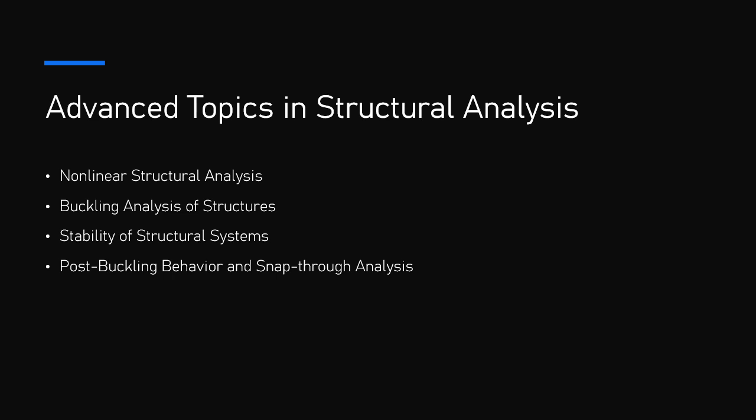10.2. Factors affecting buckling. Several factors influence the buckling behavior of structures, including: 1. Geometry of the structure. The length of a column or structural element has a direct relationship with buckling. Slender structures are more likely to buckle under compressive loads. The cross-sectional shape and size also influence buckling behavior. For instance, structures with circular cross-sections or I-beams are generally more resistant to buckling than solid rectangular sections.